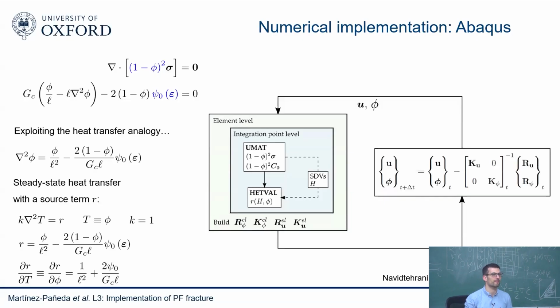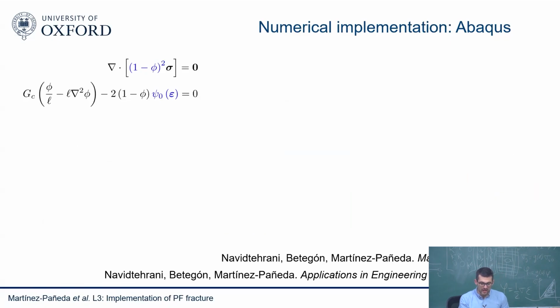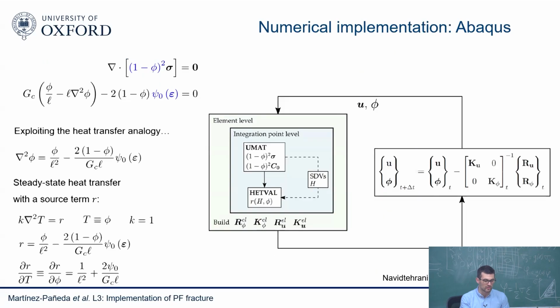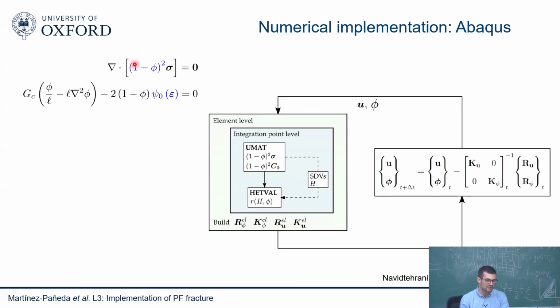Just for curiosity, how is the phase field bounded in the UMAT? Are we explicitly saying that when the damage parameter exceeds 1, we reset it to 1? No, we don't do any of that. I've seen some people sometimes do that in the UEL, but it's the equation that you're solving that will bound it necessarily. So phase field can only be 0 or between 0 and 1 based on this. So you don't have to bound anything.